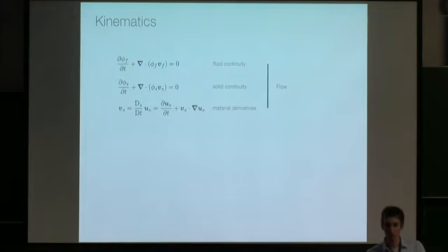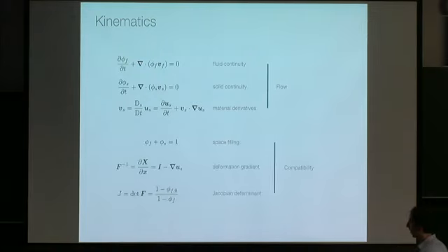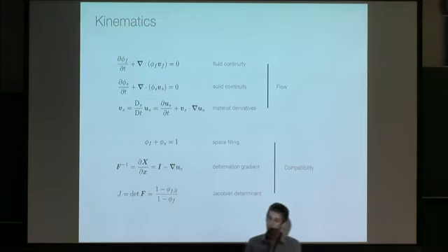And additionally, we need a bit more about the changing geometry. So we have the fact that the two void fractions, the two volume fractions, add to 1. So the u_s is displacement, yeah? Yes. And we have to introduce this quantity called the deformation gradient tensor. So this is this capital F. And I'm defining it here via its inverse, because in an Eulerian frame, this is a little bit more convenient. The idea is that this measures how much your configuration has changed from where you started. So it's a tensor that's constructed by essentially taking the gradient of the displacement field.